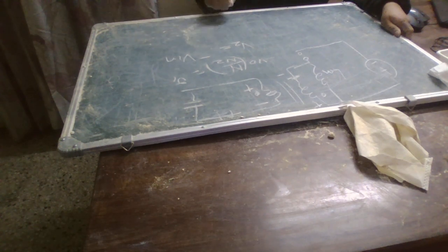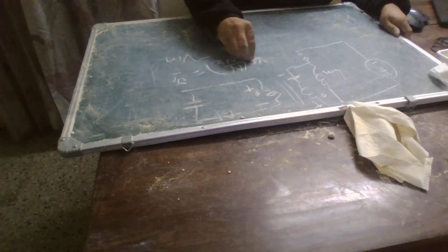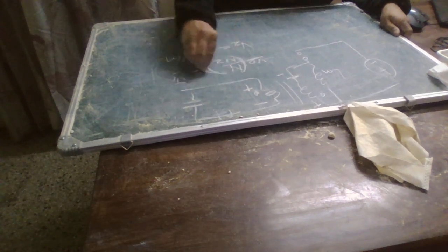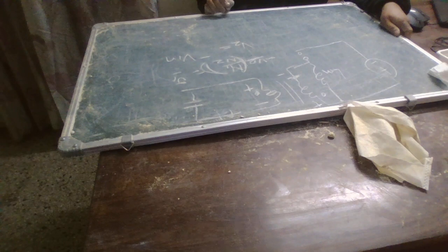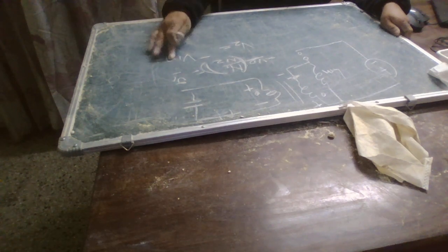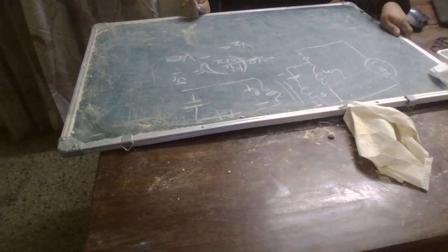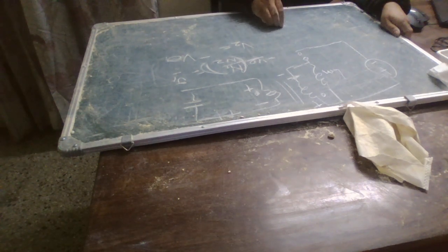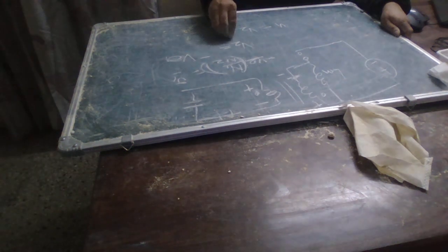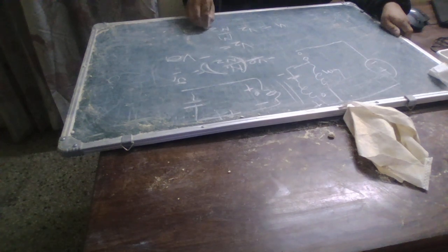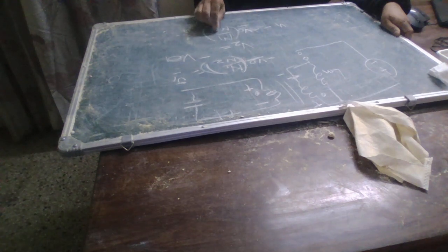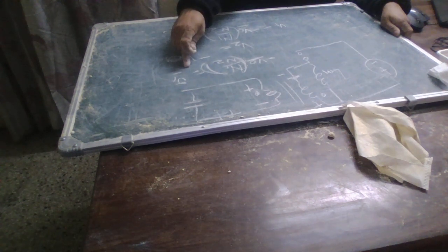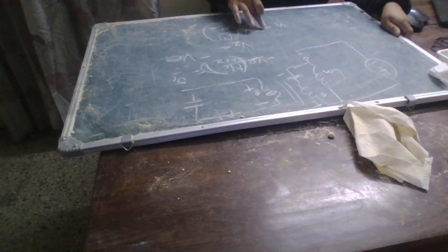So these are the voltages and the currents, because now we have a reflected secondary output voltage along with the number of turns, and that is the primary voltage level. The secondary voltage level is equal to the output voltage, and we can say V input or V1 is equal to V2 N1 by N2, that we know. Now our V2 is minus V0, so this will be minus V0 N1 by N2. That's why we have got this V1 primary voltage, which is basically reflected here.